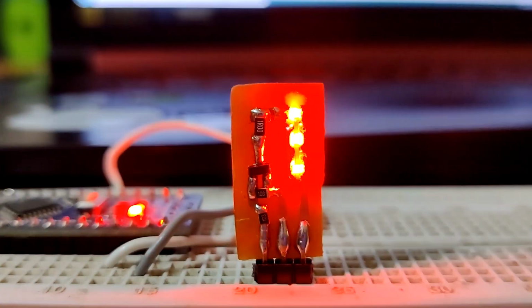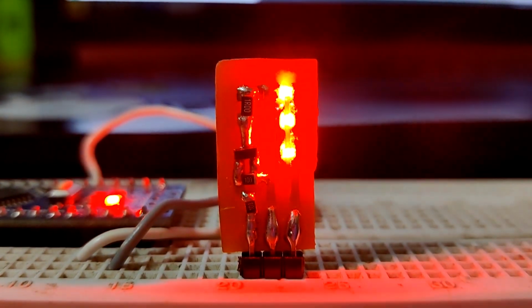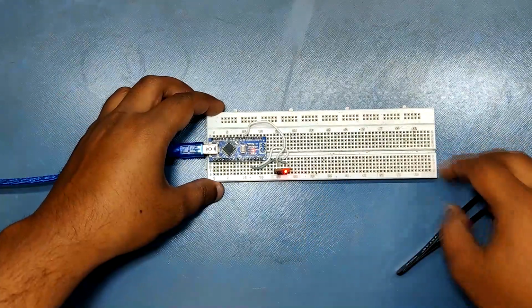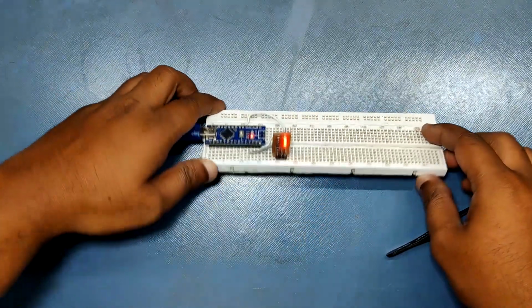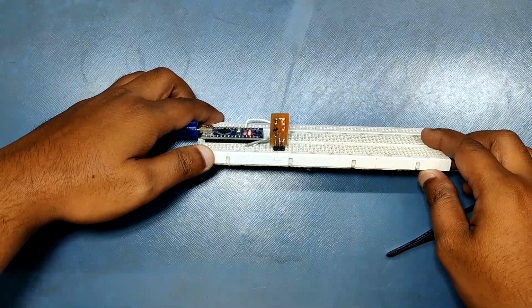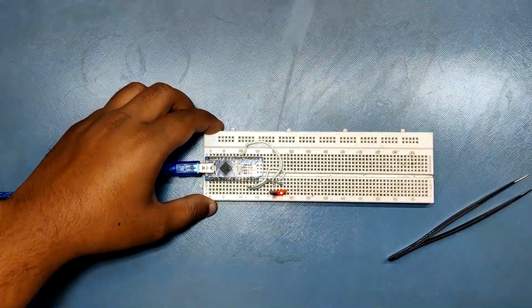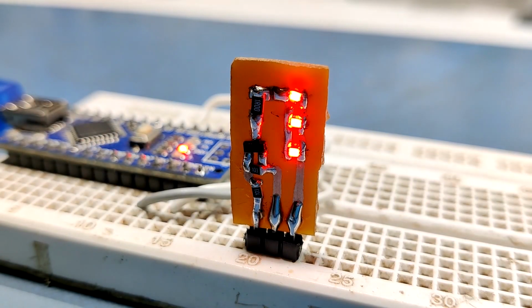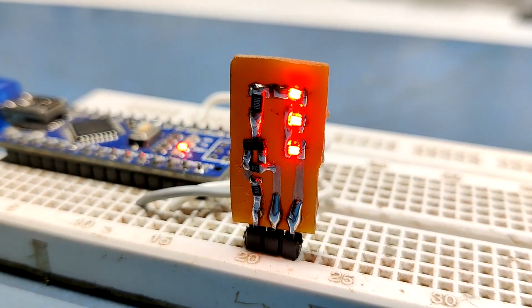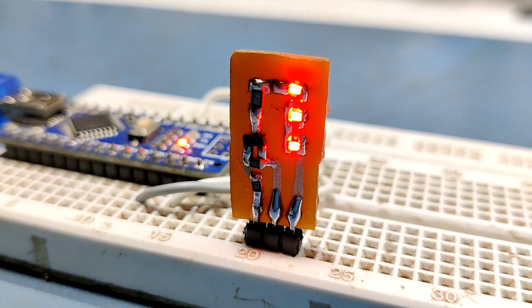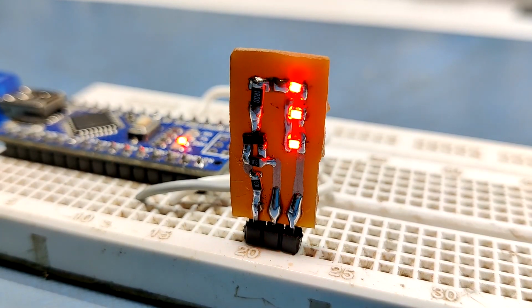After wiring, we upload a general fade sketch to our board and then power it up with any power source, which in my case is a power bank. PWM fading is working nicely in this setup, which was the goal of this build, to use a BC847 transistor to control a load, LEDs in this case.